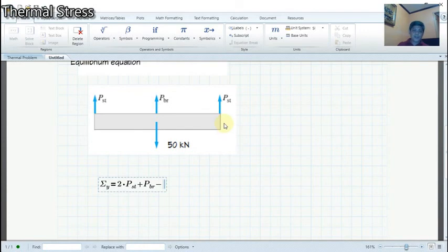And since we need to have a consistent unit, it's better for us to convert kilonewton into newton. So we will be expressing our answer in terms of newton for the force. For the length later on, we will be expressing the length in terms of millimeters, so that we will have the base units of newton and millimeters, and we can determine the stress in terms of megapascal.